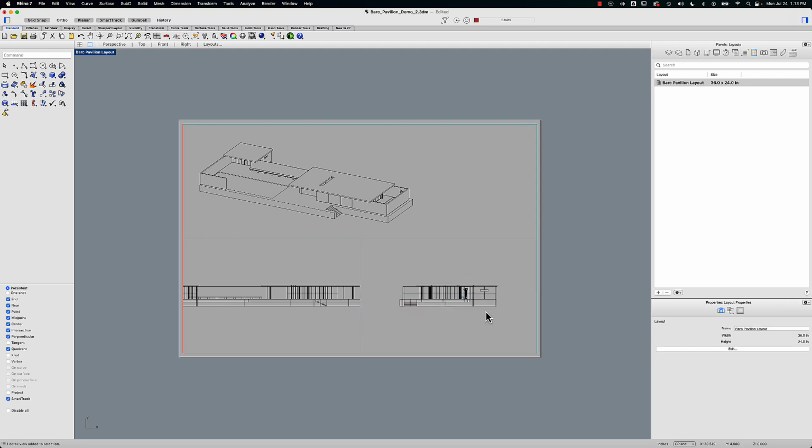And what I'm going to do now is I can actually resize these detail views. So let me just grab this. I'm going to hold on Shift, select these two control points, and I'm just going to make this a little bit bigger so I can bring most of that in view. Okay. And then similar here, I'm going to grab these 2 points and let's just drag them over here. And now I just need to reposition the contents of each of these, right?